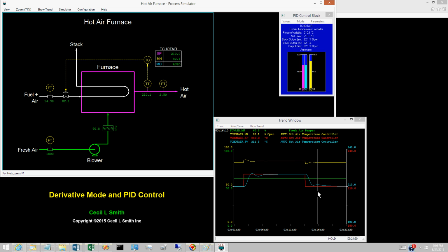As implemented in most commercial control systems, the derivative is based on the PV, but the PID equation in most control texts is expressed entirely in terms of the control error E. Some, but not all, control systems provide this option. This is the subject of the next video.